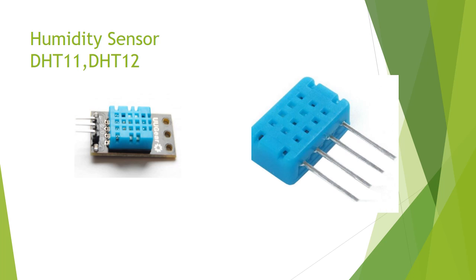In your humidity sensor, there is one more thing, the working principle. If you look around, it works on the principle of capacitance, the voltage across your capacitance. Now there is a capacitor, and this capacitor has some dielectric material that changes its capacitance with respect to the moisture.